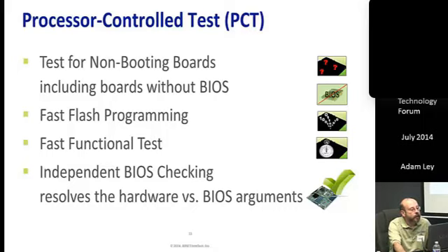What do we use it for? We use it for test and debug of non-booting boards, including boards, as we said, without a BIOS or without the ability to boot. It's also used for fast flash programming. It provides for faster functional tests because you don't have to boot the boards. And it also provides for a certain ability to check your BIOS as a hardware and software validation task.